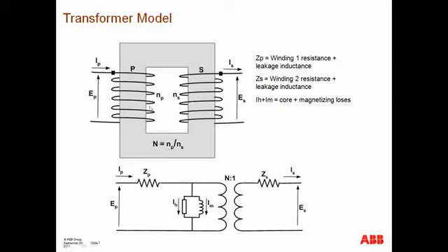So basically you have a core. In the case of power transformers, you have a core, which is usually made out of soft steel, providing a path of low reluctance to the flux. You have one winding that is connected to a particular voltage level, and then you have another winding connected to another voltage level. You could have three winding transformers, in which case you would have three windings connected one on top of the other, and we will see a picture of that in the next slide.